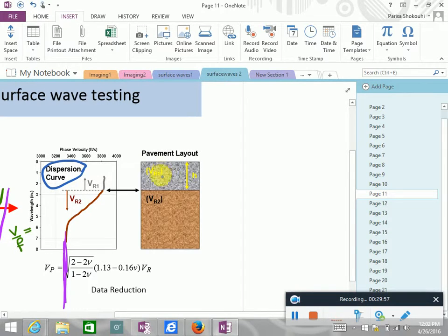So you have wave velocity 1 and 2. Can we just focus on 2 layers for now? Imagine that I assume this wave velocity. Now, this is written Rayleigh wave velocity, but this could also be shear wave, right? Because if I assume a Poisson's ratio, then I immediately get Rayleigh wave. Everyone agrees with that? Okay. So you have this. Then you want to go from here to the dispersion curve.